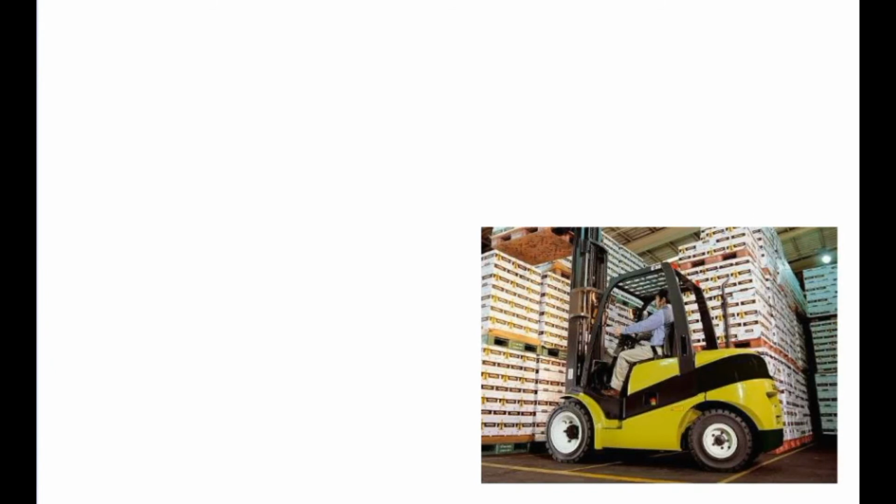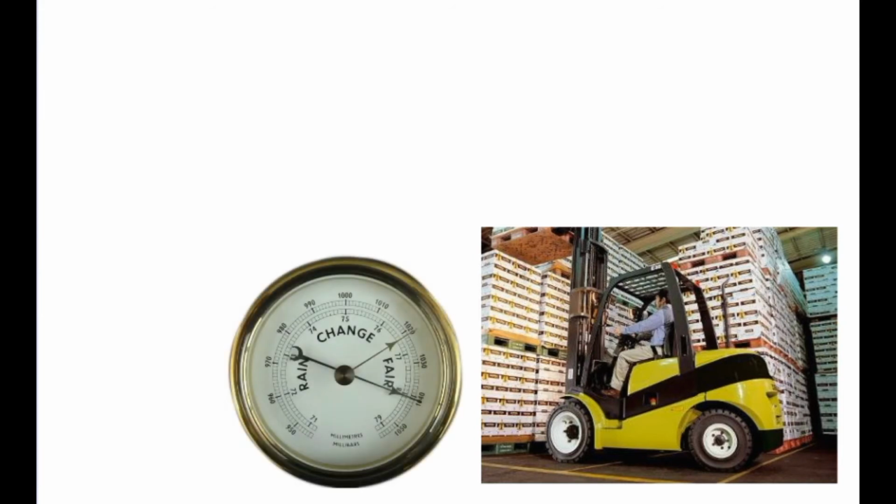The hydraulic cylinder of this forklift truck has a working pressure of 3,000 psi, whilst the truck's tire pressure is 50 psi. The air in a warehouse is at standard atmospheric pressure, i.e., 14.7 psi. These pressure values are not directly comparable, since they are values taken from different points of reference. The pressure of the air in a warehouse is due to the gravitational pressure of the atmosphere. If there were no atmosphere, there would be no pressure. The reading on a barometer would be 0.